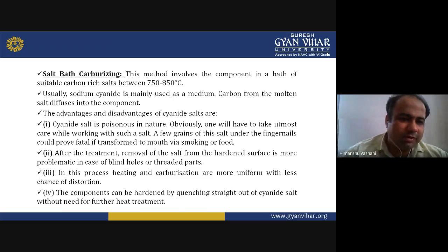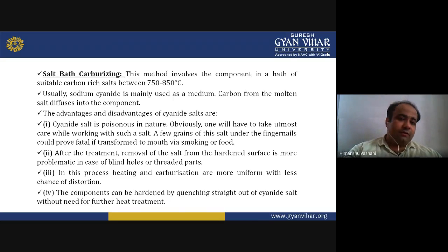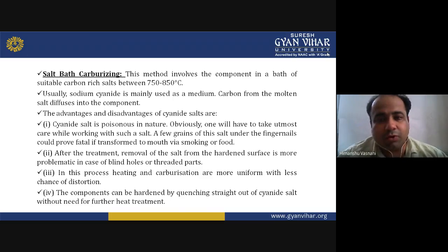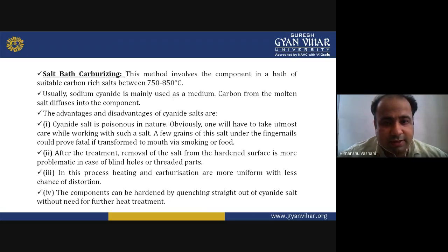Now, the advantage and disadvantage of this cyanide salt. The salt is poisonous in nature, so obviously one will have to take utmost care while working with such a salt. A few grains of this salt under the fingernails would prove fatal if transferred to the mouth via soap or smoking or food. After this treatment, the removal of the salt from the hardened surface is more problematic in case of blind holes or threaded parts.